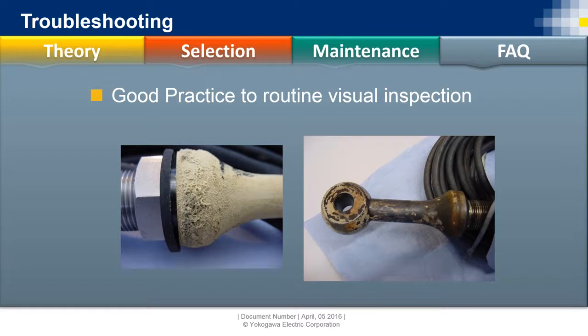Here's another one. Be cautious of those inductive sensors. Literally, you can put one of those inductive or electrodeless sensors in line and it will last probably years. But they do fail over time, so it's good practice just to visually pull it and check it. I don't know how frequently people do it, but I would say probably minimum once a year, or you may have standard procedures that when the line goes down, go check it just to be safe, because they do give way.